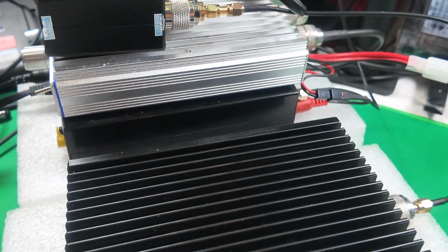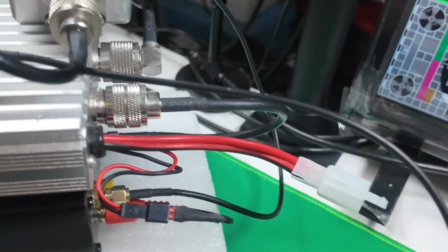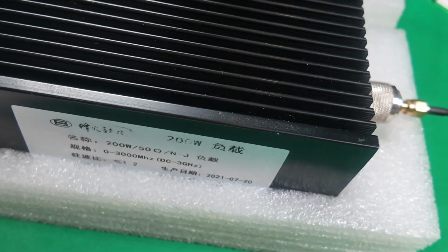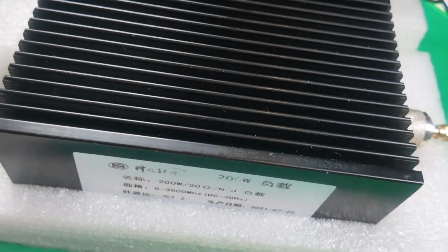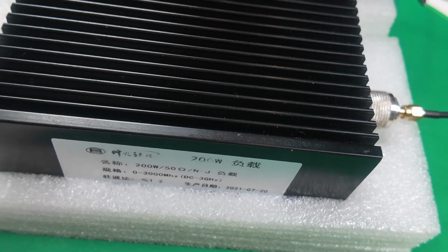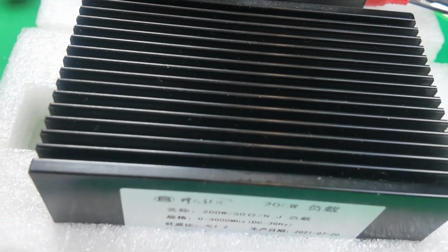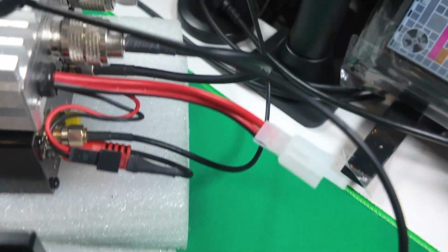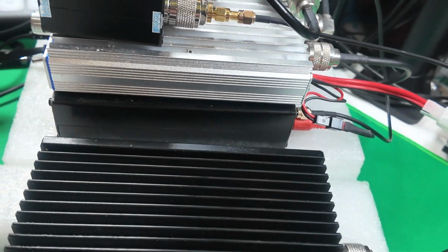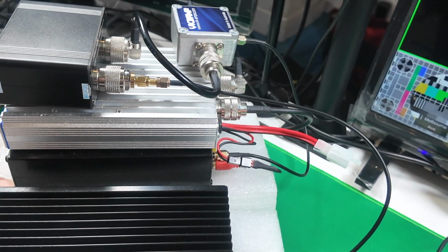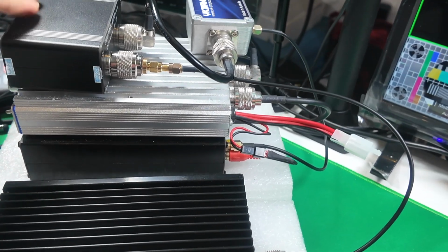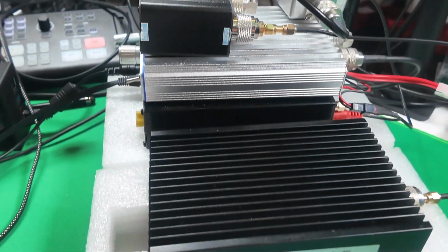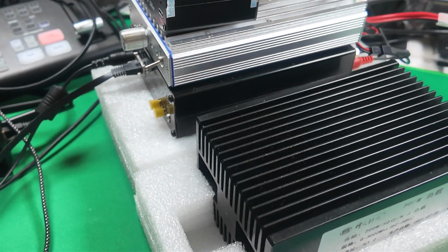Oh, by the way, I did not show you that the output out of the Hermes is actually going into a dummy load. This dummy load can handle 200 watts. It's pretty good and very linear. It goes up to 3 gigs, and I put it on a VNA, and it is pretty flat up to 3 gigs, so that's pretty good, and 200 watts. So I thought it's best to run it through a dummy load rather than just even low power transmission, because I'm doing all sorts of mucking around with the Hermes and I don't want to blow it up. So that's basically the dummy load that sits below the Hermes.